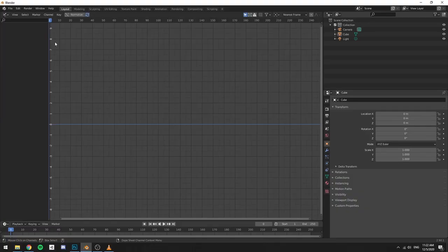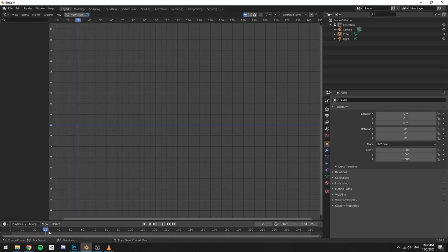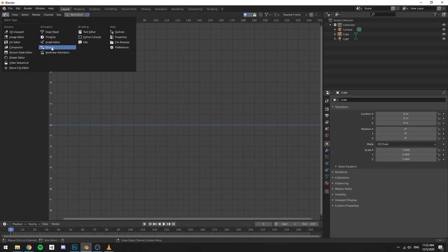Let's move on. The graph editor. When you place different keys, those keys create curves, and those curves can be manipulated in order to create different motion. You can create ease in animations, ease out animations. So pretty much in the graph editor, we're going to be doing that.